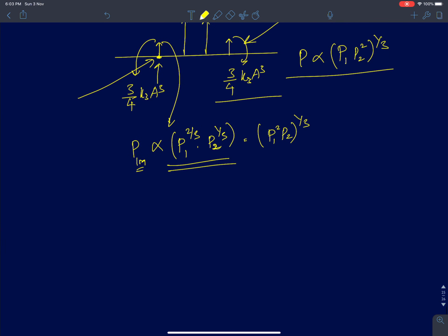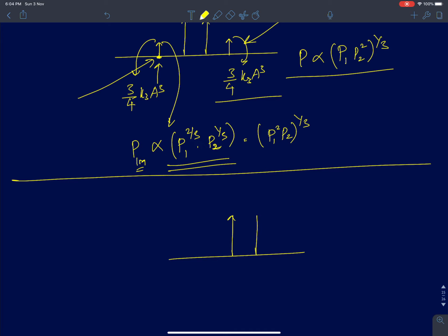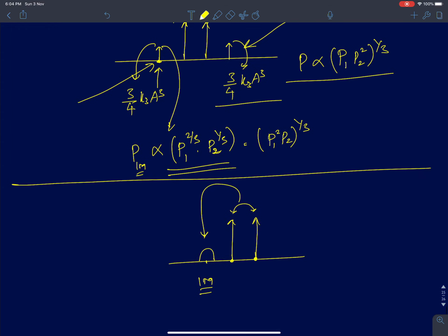Now, what is the main goal of discussing all this? In an RF system, we said we will not just have a single interferer. We saw that a single interferer was causing gain desensitization, or it can even completely block your signal. Now if I have two interferers, they might also cause gain desensitization, but they will also introduce a component at your signal of interest. This component is called the IM, intermodulation component, or IM product.